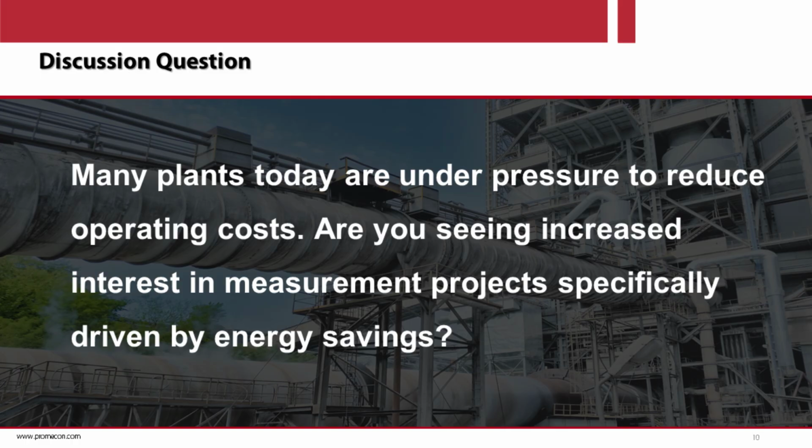When you integrate continuous air or flue gas flow measurements in a control loop, either as a set point or a correction to that set point, they do enable reductions in ID fan power consumption. Or in another part of the plant, it allows the mill's output to increase while keeping the same quality, fineness, for instance, by optimizing the airflow through those mills.